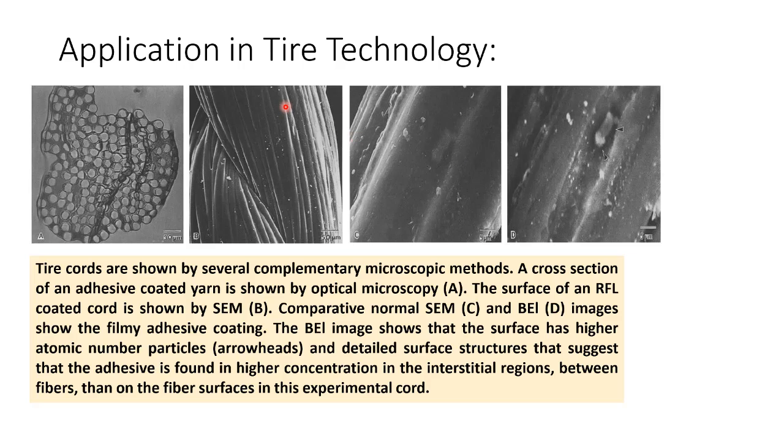So again, in tire technology also, this has very good application. Tire cords are shown by several complementary microscopic methods. A cross section of an adhesive coated yarn is shown in the optical microscopic image. So this is the optical image. The surface of the RFL coated cord is shown by the SEM. This is the SEM image.